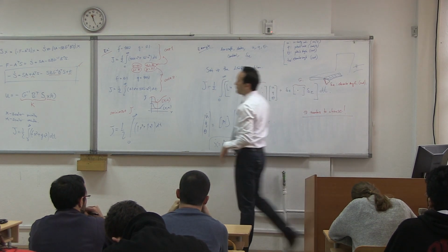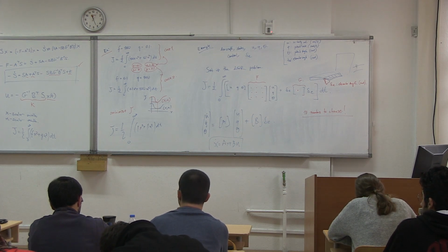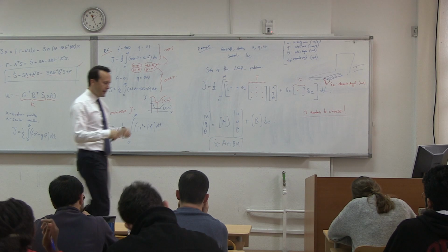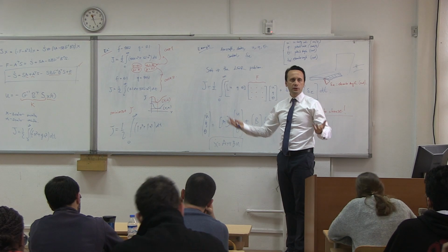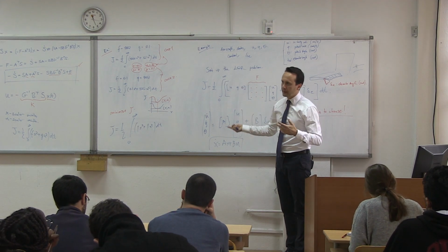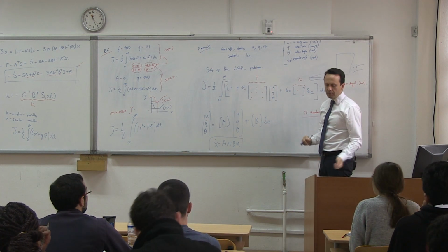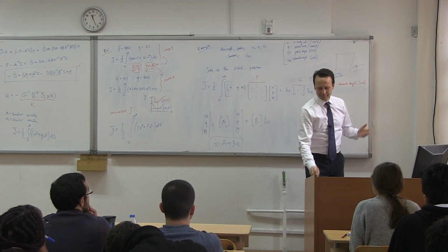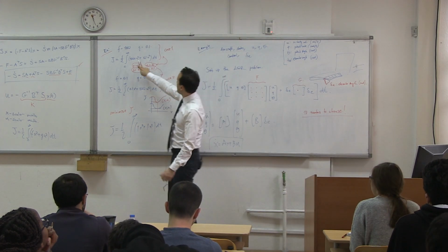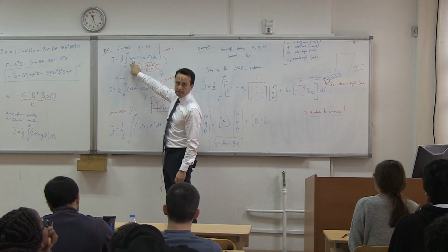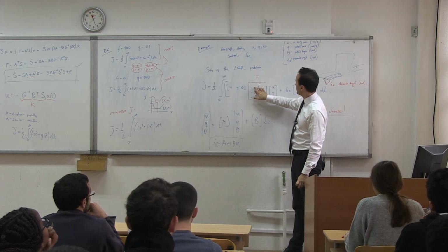If I can choose F and G, all I'm going to do is write this one, solve the algebraic Riccati equation, find the feedback gain K, and this is what I would call my LQR gain. And what we are trying to do is still optimal control, because there's an optimization problem that we are solving in the back. Okay? So, how do I choose F and G? Here is how I would do it, typically. Okay? First of all, if you look at this problem, we had x squared times 1000. Remember? Okay.